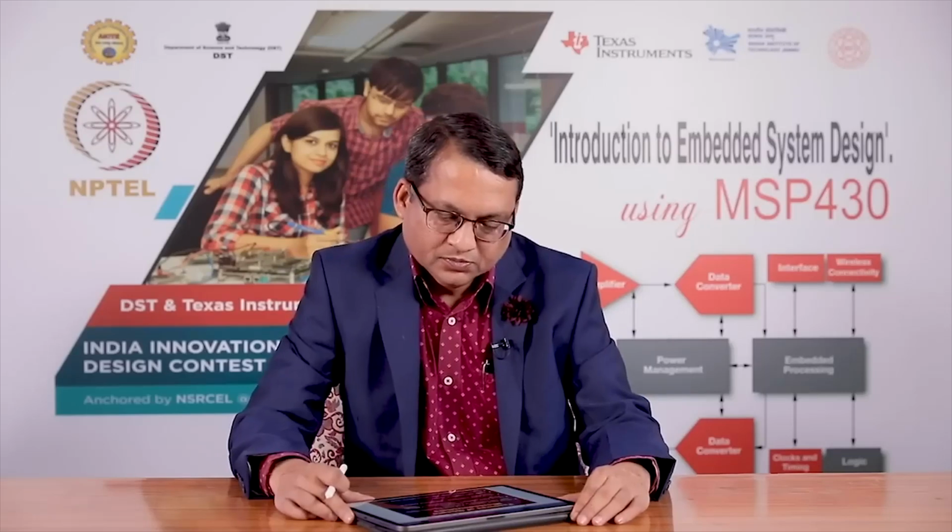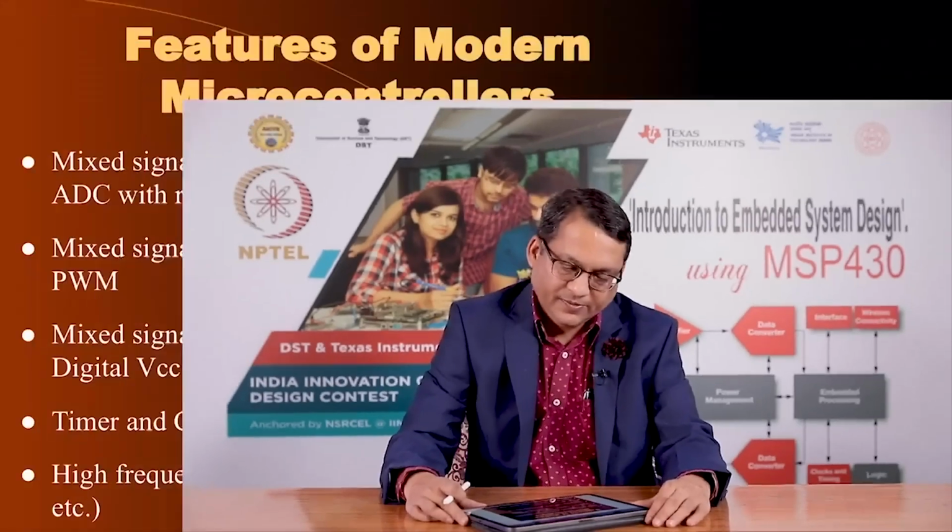So, this is an important point to keep in mind when you are designing a system using a microcontroller: does it have a common pin, or does it have independent pins for the VCC of the analog part and the digital part of the circuit?